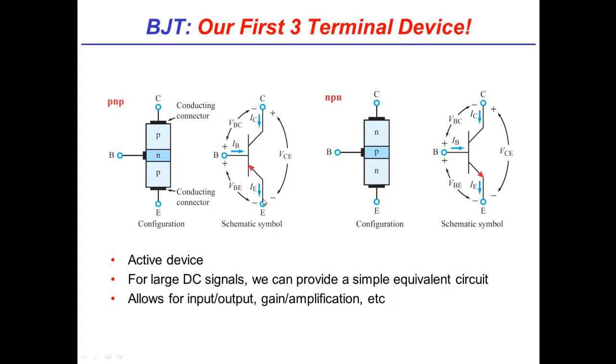So, Michel, if I remember what we learned some time ago about KCL, I'm assuming that if I were to draw a box around that bipolar transistor, IC plus IB should equal IE because of the way you've drawn those arrows? Yeah, that's right. IB plus IC coming in must equal IE coming out because there's certainly no other place they're going, and we're assuming that nothing in here is charging up for the purposes of our DC signals. So we're making it pretty easy on everybody. Yeah, that's absolutely right. You're kind of getting ahead of ourselves.